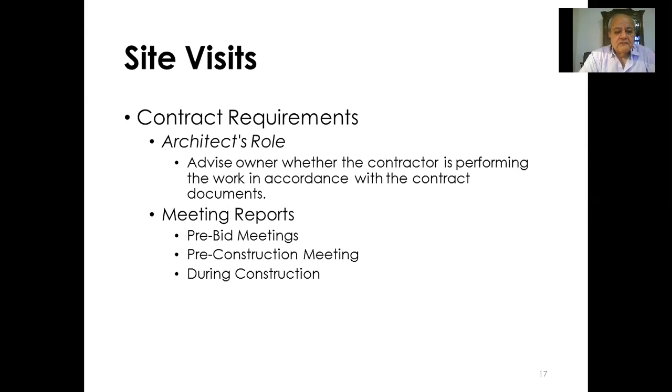When you're saying if there are major changes, I have to go back to the contract documents before and re-edit them. Yes, you have to. You have to issue a change order that has a modification of the contract, and modification of the quantities and the drawings of the part that is changed.